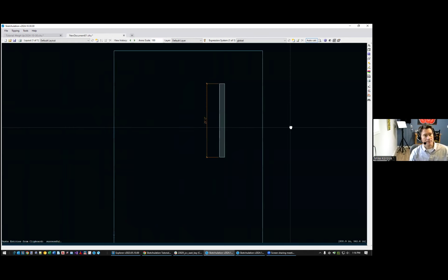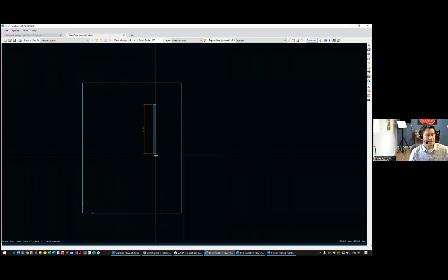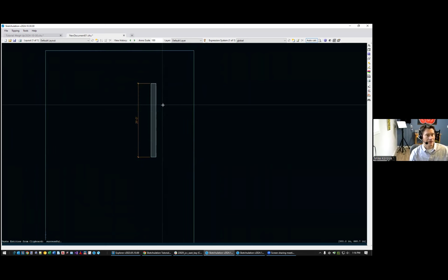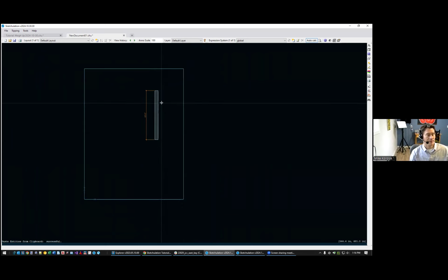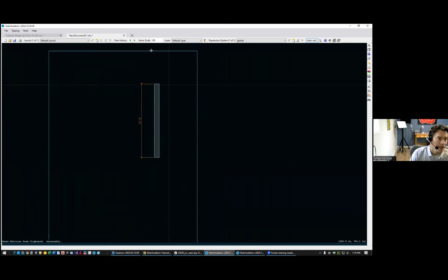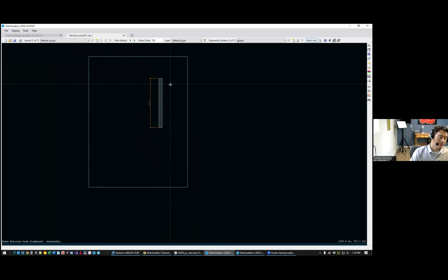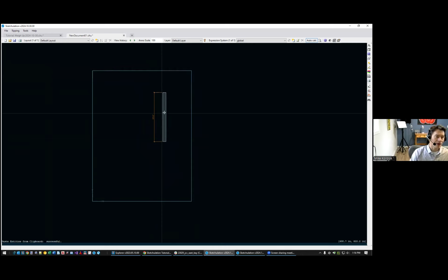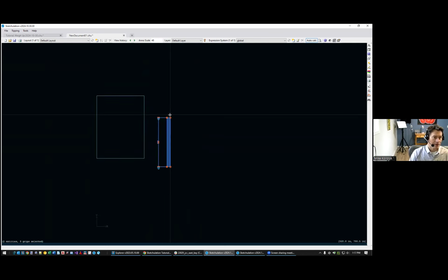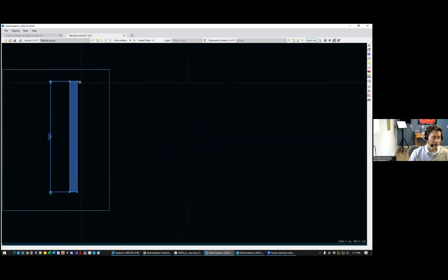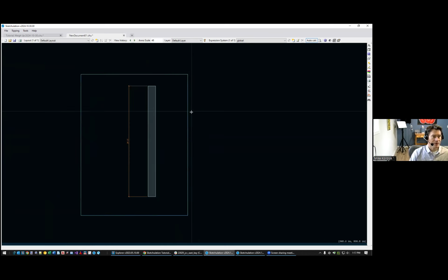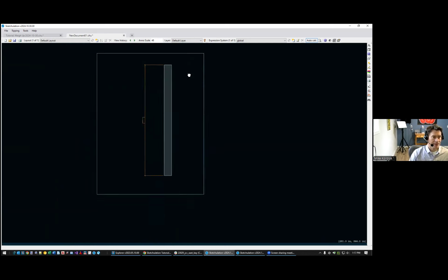And this fits nicely on the page, although for my section analysis, I'll probably want to make this somewhat bigger. So I want to make my page smaller relative to the wall, so the wall takes up more page space. And so then that means I'm going to want to decrease the annotation scale. So I think maybe 48 would be a good guess. So I put that in there, and I see that fits pretty well. This will be a nice calculation page.